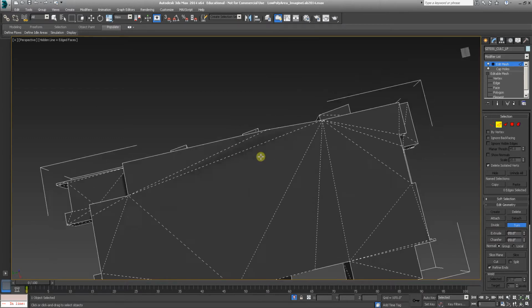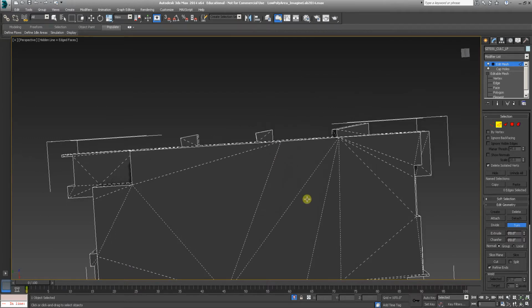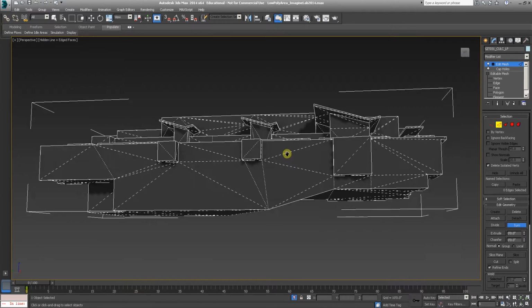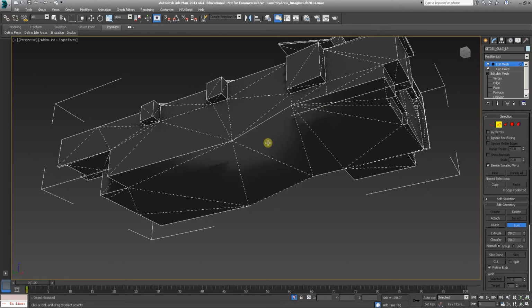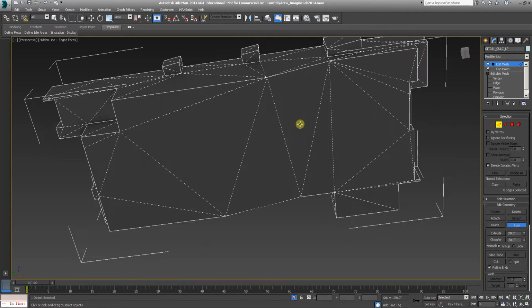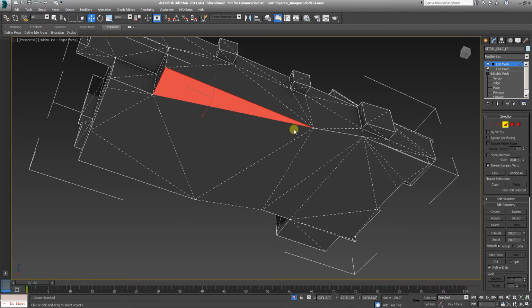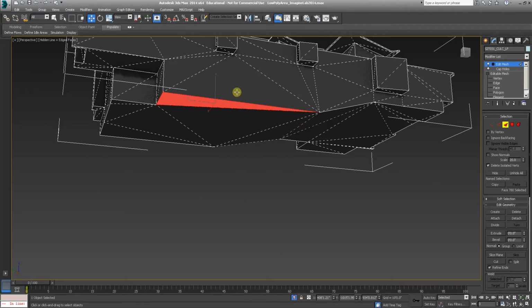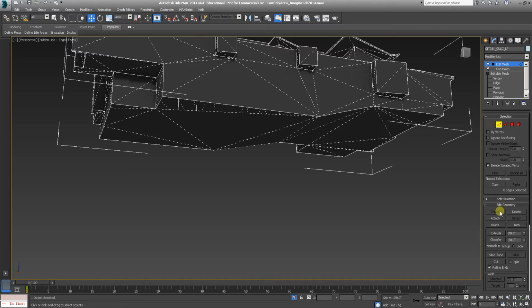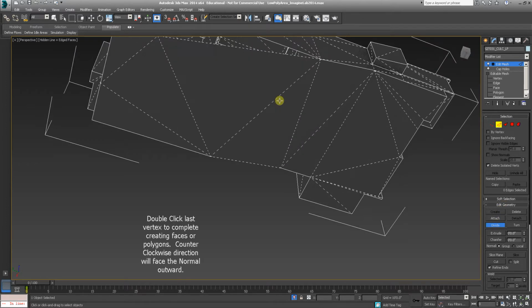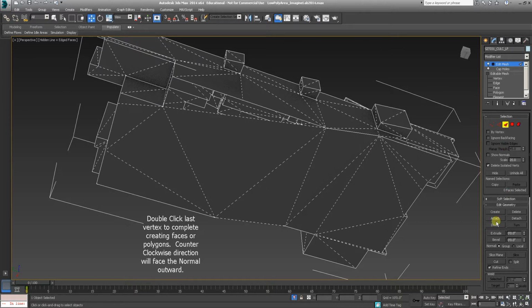Yeah, so turn a few more here, and this will give me a lot nicer ramped progression rather than a bunch of edges turned on each other. You can do things if you're missing, let's say you had a vertex on this face but not one on this face. Let me delete that and I'll create it real quick. So I'm just going to divide that face and add another vertex in there. And then I'll recreate the one that I deleted so that we can simulate the problem here.